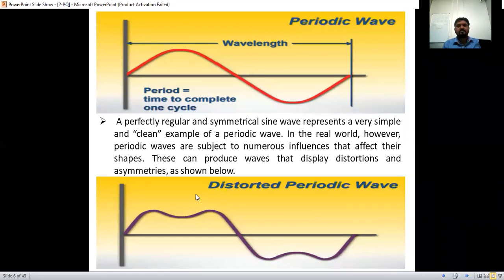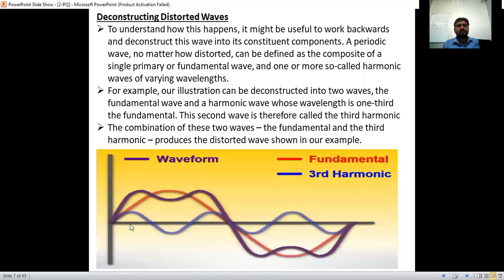These are the terms. This blue color is the harmonic waveform. These are the harmonics: 1, 2, 3. For half cycles, 3 plus 3 is 6 half cycles, which is nothing but 3 full cycles, so we call it the third harmonic. This chocolate color waveform indicates the periodic waveform.